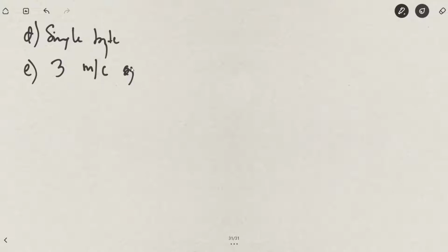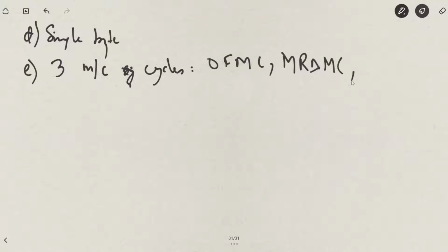Just remember, these 3 machine cycles are now opcode fetch and memory read machine cycles. So you will now have 2 memory read machine cycles instead of memory write machine cycles, because you are now reading from the stack pointer and storing that onto the register pair.